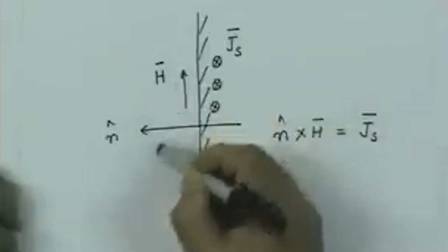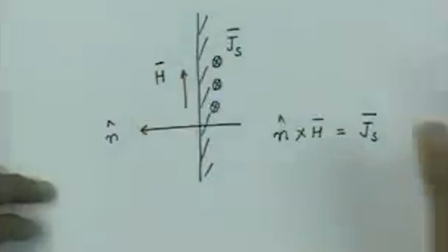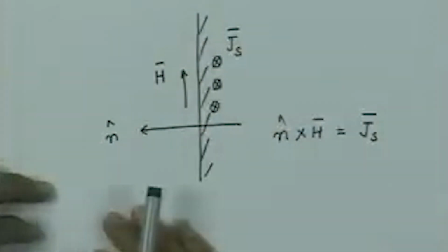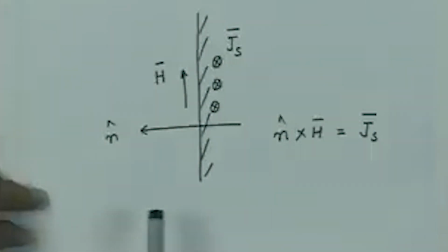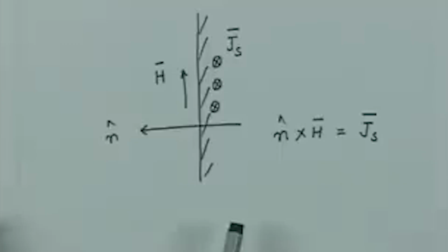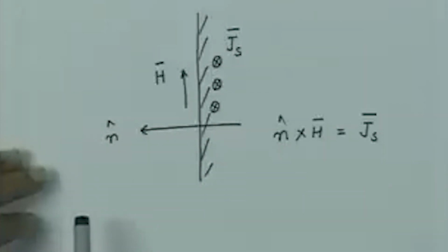The power which goes with this wave inside the conductor is the one which is lost in the ohmic losses of the conductor, because the medium is infinite and this power decreases as the wave travels, and no power comes back. So, equivalently, whatever power flows inside the conductor is a measure of the loss inside the conductor.